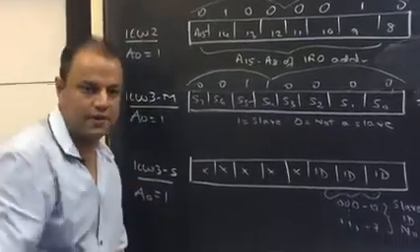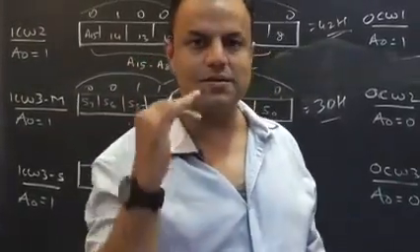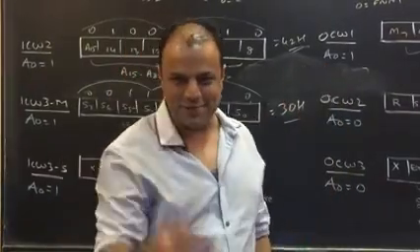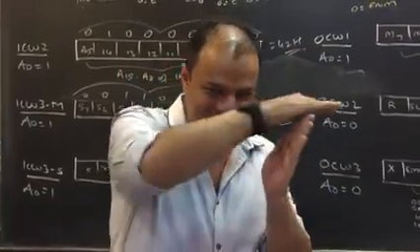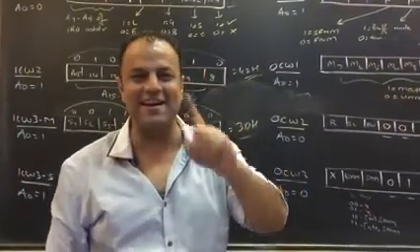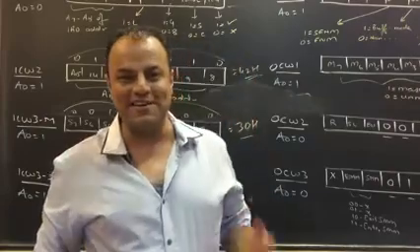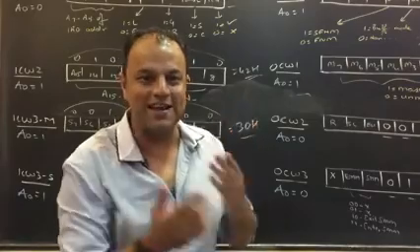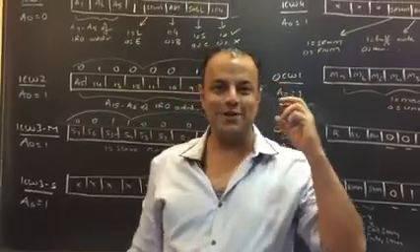There's another ICW3 that you give to the slave. What did you tell the master? On which lines there are slaves. What do you tell every slave? Try to remember. You tell every slave on which line it is connected to the master. That means you give every slave its identification number. Is that number important? Super important. That is the number which the slave will compare with the number that appears on the cascade lines. There are how many cascade lines? 3, because the number can be anything from 0 to 7, 000 to 111.